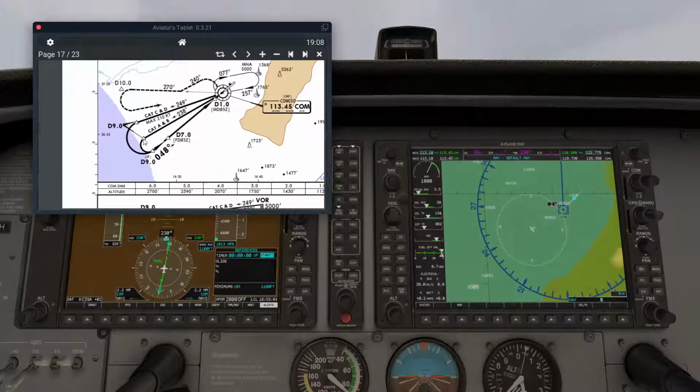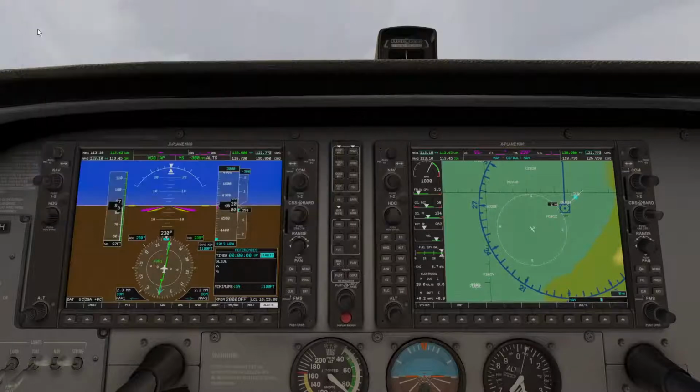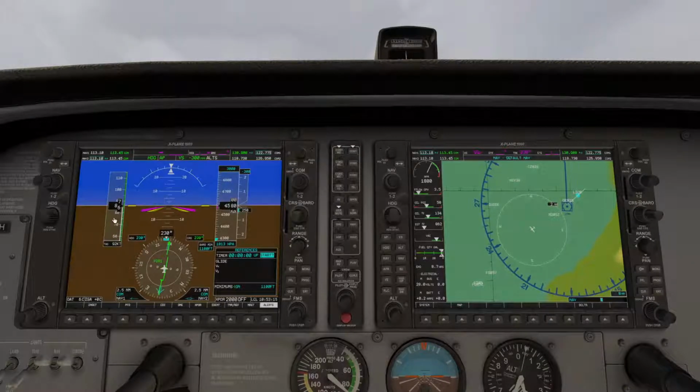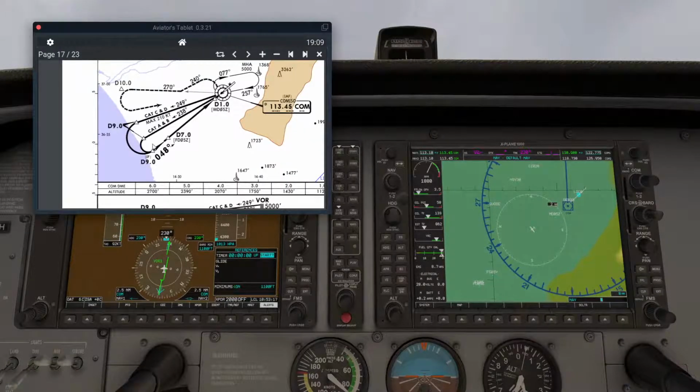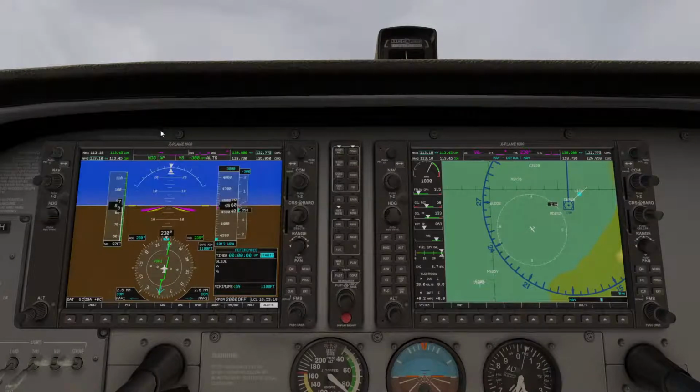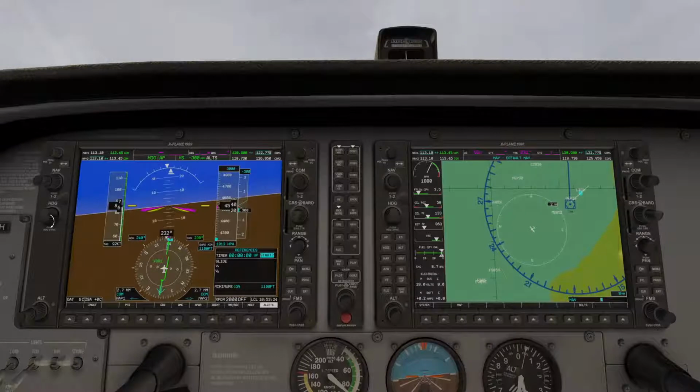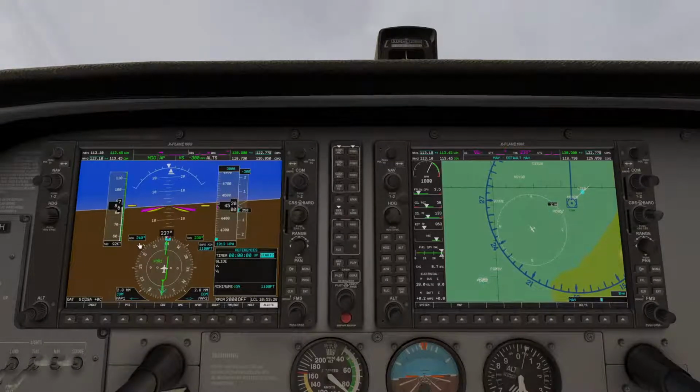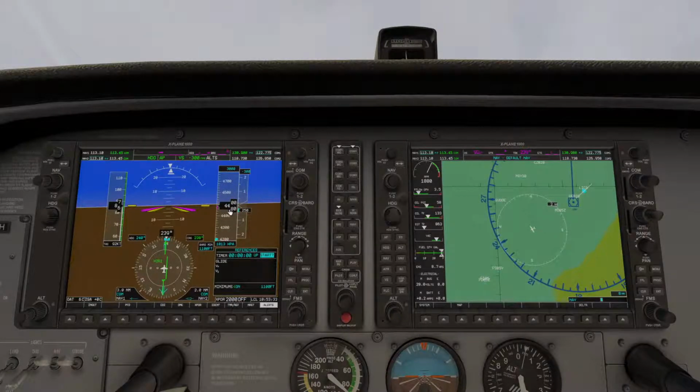We will continue to 9 mile out of the VOR, and currently the 2 mile passed. Actually about 4 minutes we have to reach 9 mile on course 238. The CDI passed and proceeding on heading 240. 4 minutes and 1,500 feet.